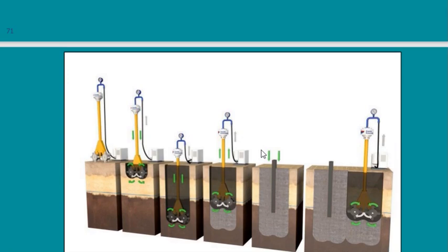I had a full wall with the width of the rectangle section, because it's just pieces of wall next to each other. Of course, I do one and I leave one and I leave one, and then construct the ones in between. I will end up having the full length of the wall as if it is one unit connected to each other.